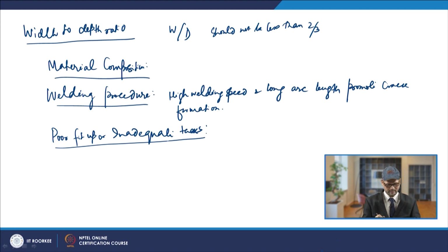Similarly, if you are providing inadequate tacks, that also leads to cracks. So, these are the factors which are responsible for the formation of hot cracks, especially the solidification cracks which are occurring in the weld pool.